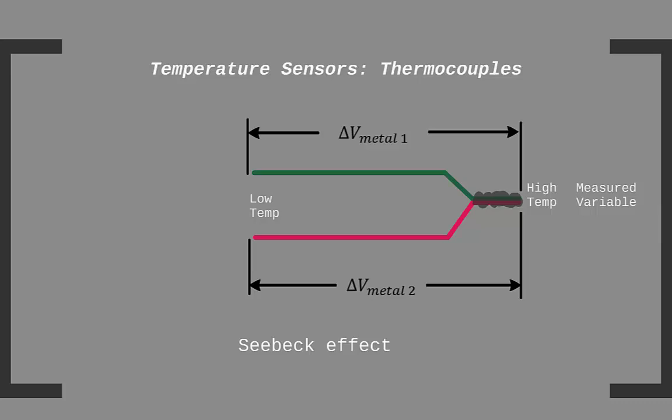The other unjoined ends are brought in contact with the location of known temperature, and the voltage difference between these ends is measured. Based off the voltage read, the temperature difference between the location being measured and the reference temperature can be determined. The issue here lies with having to know what the reference temperature is, to be able to know what the temperature you are measuring is.